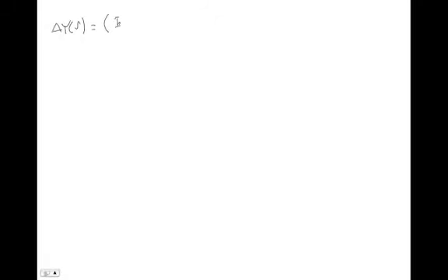It looks like the identity matrix plus C (sI minus A) inverse L, and this is a big matrix, and that's inverted, times C times (sI minus A) inverse, and this is times our disturbance now in Laplace transform. So this whole thing here is the Laplace transform that goes in front of disturbance. So it's the transfer matrix from disturbances to errors in our output y.